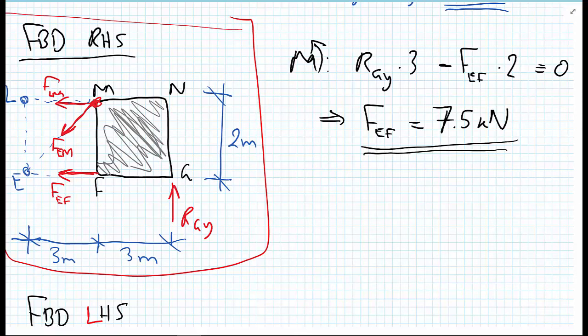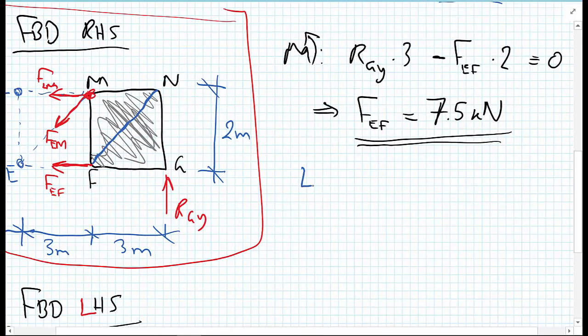However, before we can do that, to be able to get the sines and cosines, we need the length of any of these horizontal members. In this truss, we're lucky, they're all the same length. So it's just a quick calculation, length EM, I'll use L for length, equals square root of 2 squared plus 3 squared equals the square root of 13.